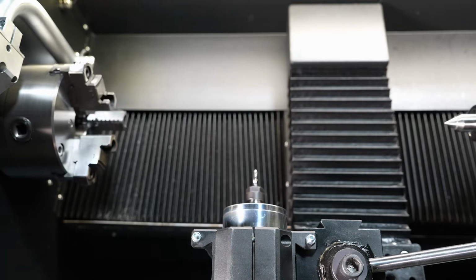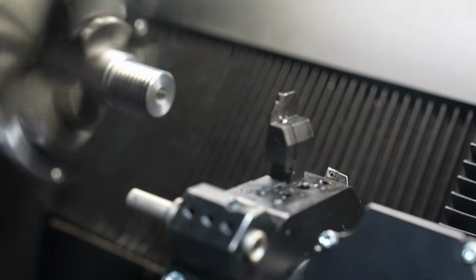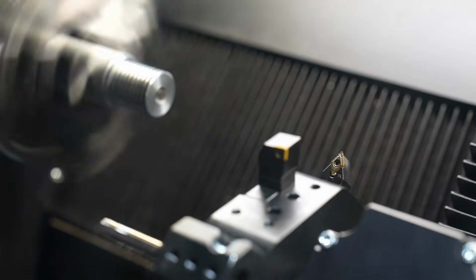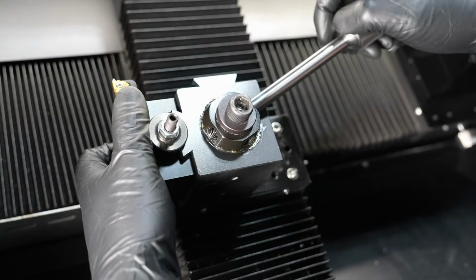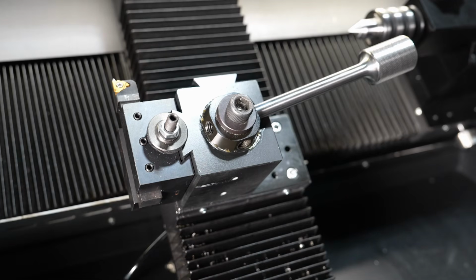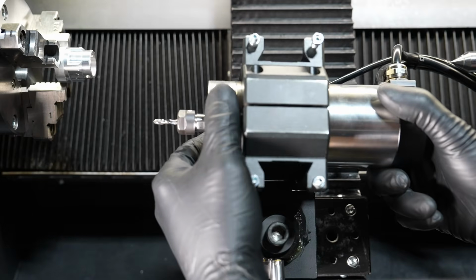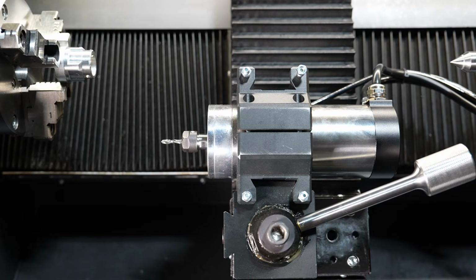The main thing that changes between these modes is how the machine handles tooling and axis behavior. In ATC mode, the automatic tool changer is active, and tool changes happen automatically. In Manual Tool mode, the ATC is disabled, and tool changes are done by the operator. In Live Tool mode, the ATC is also disabled, but the C-axis is prepared for index positioning, so the machine can perform live tool milling operations.